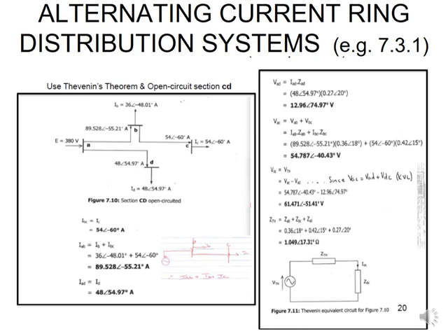Then you're left with the portion that we open circuited, which is your VDC. In this case, we say that is going to be equivalent to our Thevenin voltage. And so that voltage is really your VAC section, subtract your VAD section.